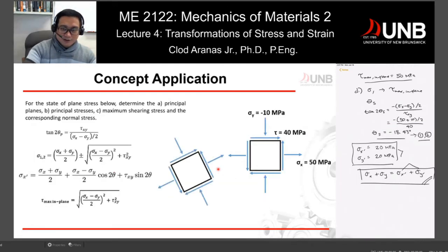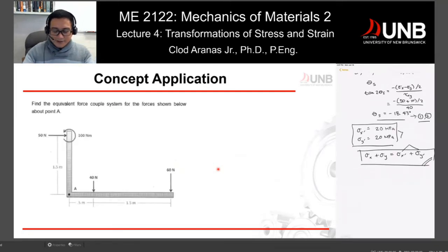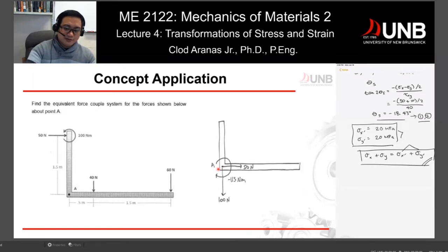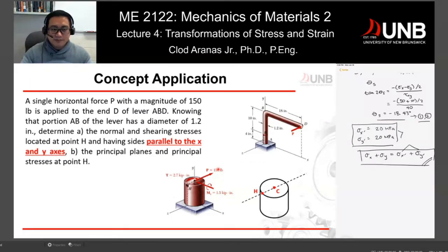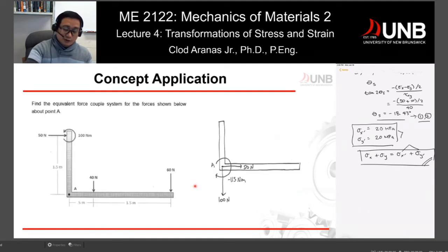Okay, so let's move on to the next one. Those were very easy analyses in terms of getting principal stresses and the rotation to get your normal stresses and maximum in plane shear. But let's look at this one right here. This would become a more complex problem if we consider a three-dimensional problem wherein we are asked to analyze, for example, the principal stresses at point H, or the maximum in plane shear stress. So that becomes a problem when we go from a 2D problem to a 3D problem.